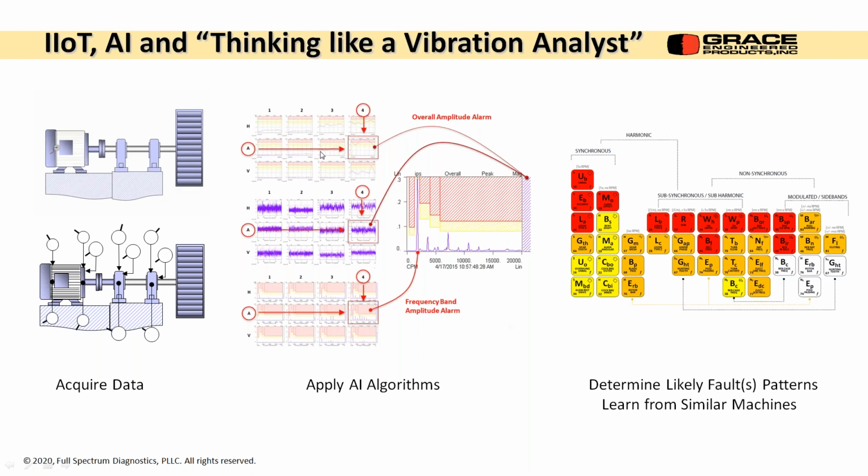Right now, we're doing little packets of overall levels, so we're getting the least diagnostic information. But if something changes and goes into alarm, that prompts us to take a spectrum and a waveform. And we don't have to take it everywhere. We can target the location that the alarm came from. Once we have that, we can start using this type of logical sorting mechanism that will be able to tell us what the root cause of the problem is.